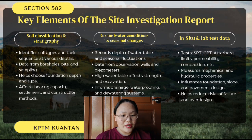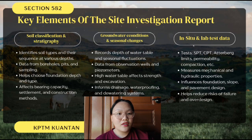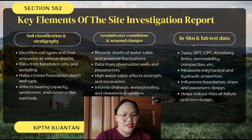The data is collected through boreholes, test pits, and sampling. It helps engineers choose the right foundation depth and type, and also affects design decisions like bearing capacity, expected settlement, and construction technique.